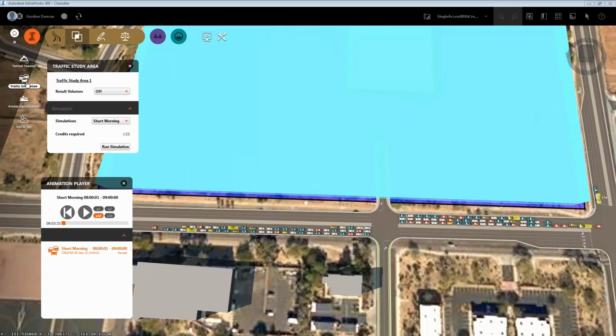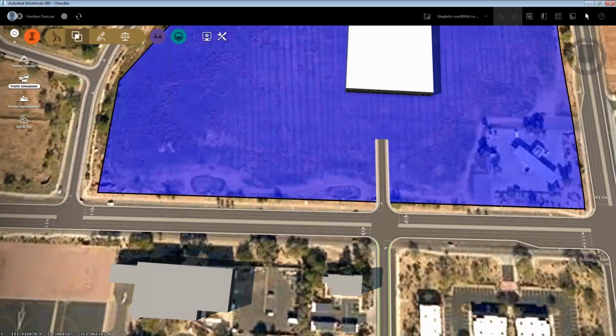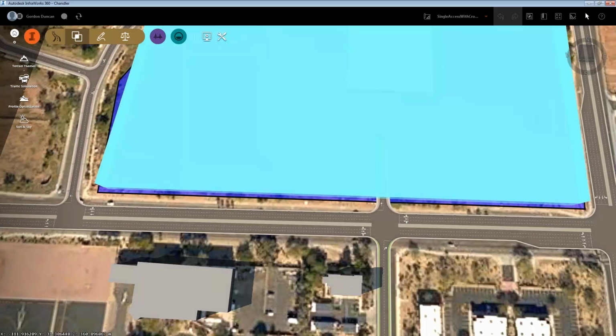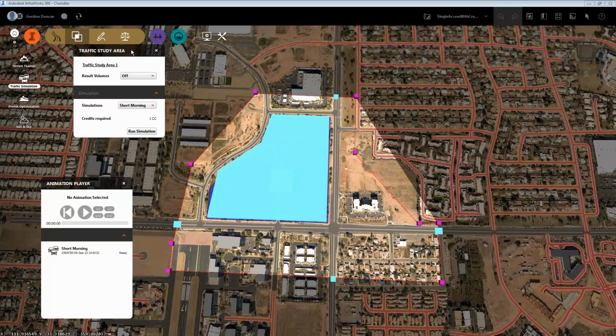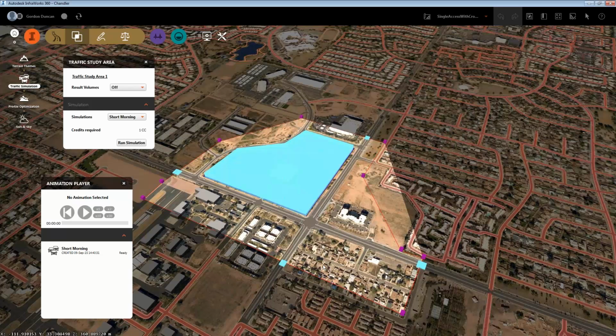So if you, actually, not sure that you can. Normally when I capture the video from there, I use a third-party tool. Okay. There is a tool within here called Webcast, but actually in this, I'm getting ahead of myself, in the September release of InfraWorks, the Webcast doesn't work on the traffic simulation part, so you need to use a third-party video capture tool in order to do that.